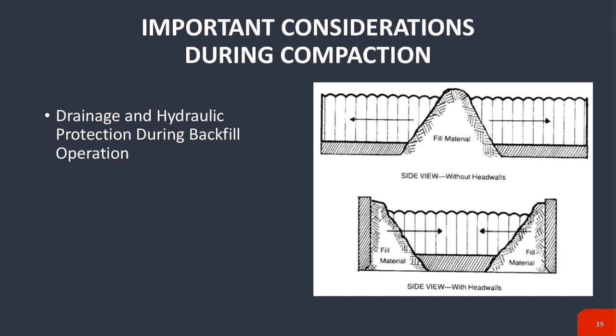So let's just talk about a couple of little special considerations during backfill. Hydraulic protection during backfill is very important. If you've never seen a pipe that's been installed and then overnight you get a really heavy rain that you weren't prepared for, it's an interesting sight. Typically that pipe goes from a horizontal installation to a vertical installation very quickly. So like I say, a lot of times this water kind of goes where it wants to go.